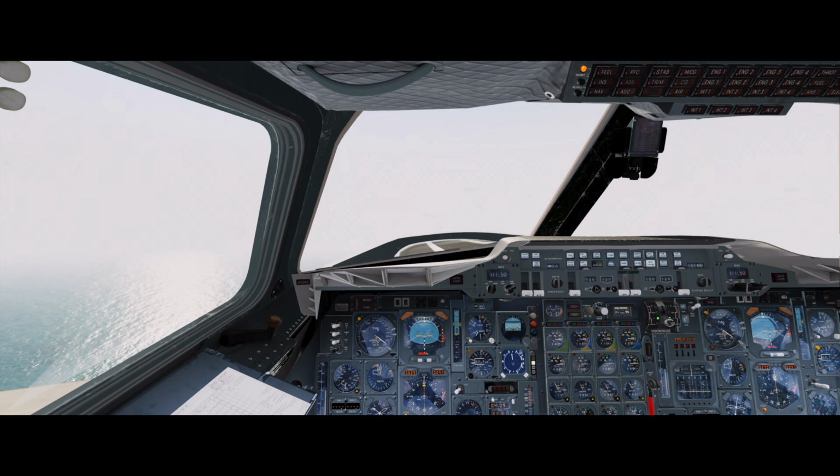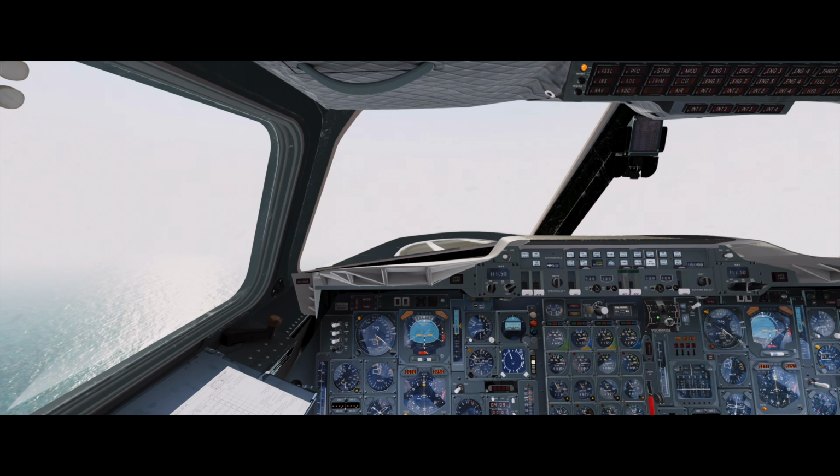After takeoff checks, please. Landing gear. Up, lights off, neutral. Landing lights. They're all off. Master warning. Recalled. That's the after takeoff checks, complete with the nose still at 5.